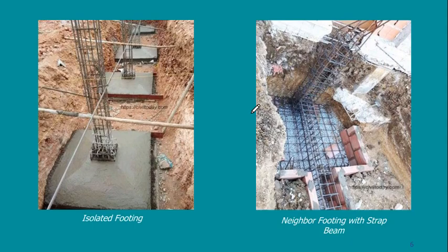First, this is the shape of the reinforcement just before casting the concrete. So this is the column at the edge of my site, and this is the footing. This column should have been here at this location, but now I have to put it at the edge. In this case, it is exerting a moment on this footing.